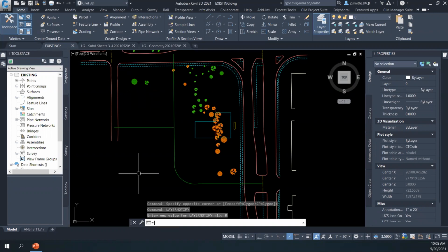The other one is going to be LAYEREVAL. Now, you should probably use the CTL, but if you use the LAYEREVAL command here and set that to 0, it'll do the same thing. But I'm going to use LAYEREVALCTL, and then turn that to 0.